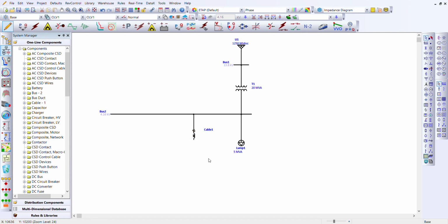After connecting the cable, we pick a transformer, another transformer, a 2-winding transformer to be precise. And then, okay, let's use our auto build. We'll pick a cable to make it faster. We connect a transformer. Now, if we notice, there's a bus automatically inserted between the cable and the transformer.